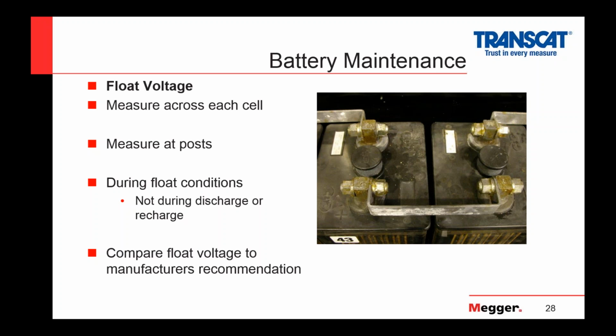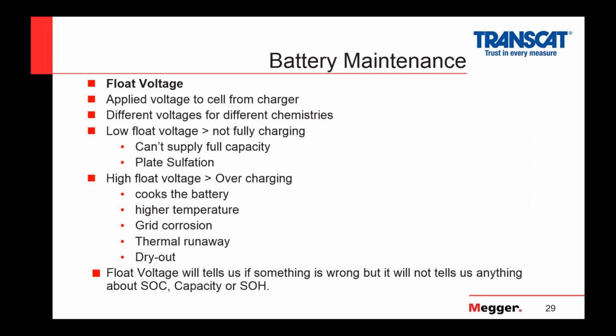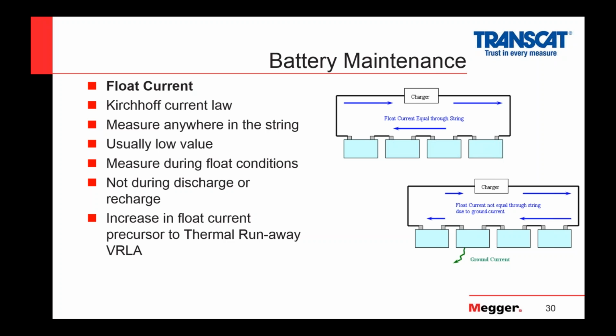This is critical. If you have it too high, you're going to accelerate corrosion. And you could accelerate dryout. If you have it too low, you're going to have plates that remain partially sulfated. And that's what this slide was all about. Next slide, float current.